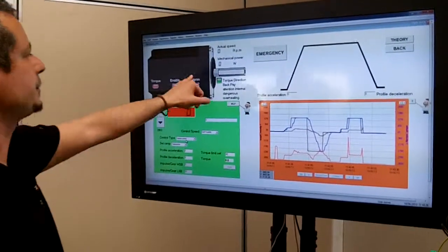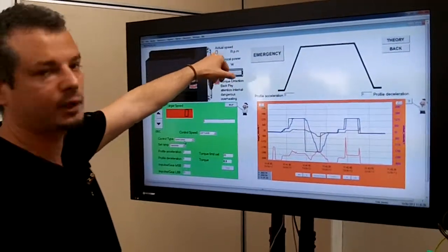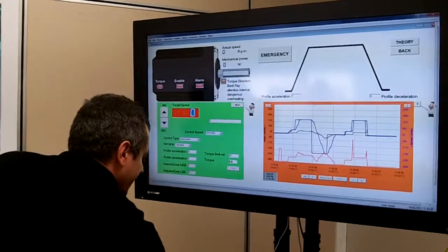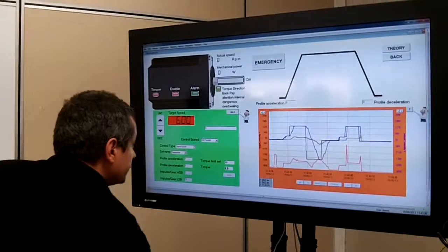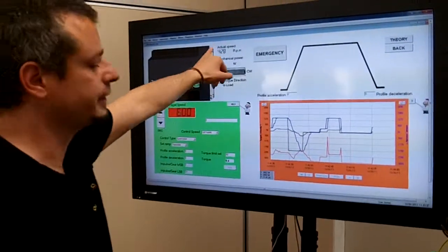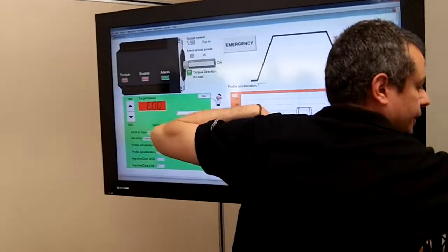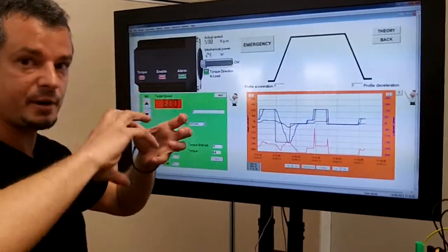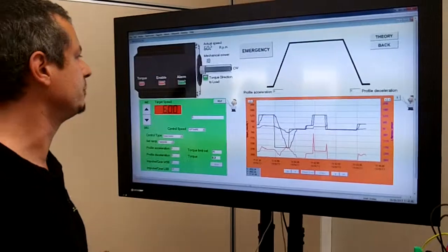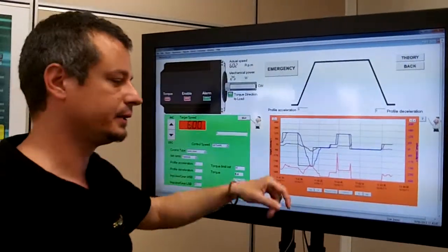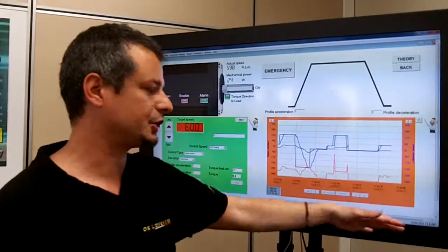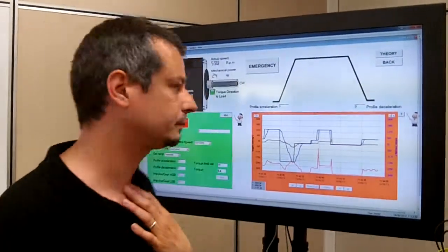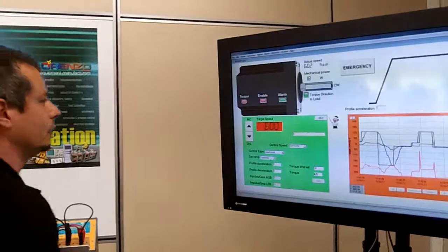Okay, here you can see the mechanical power and the actual RPM, because we set the target here at 600. There is an encoder inside. This is the signal line, and this is the actual speed. There is the vibration, as you can see in the movement. This is the power that the brushless needs to move the shaft of the alternator.